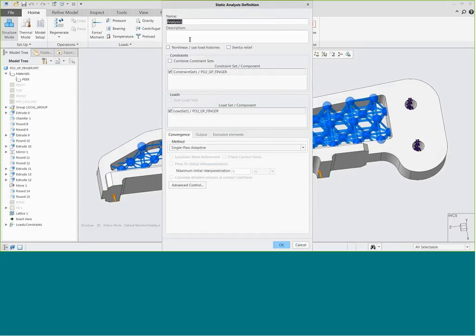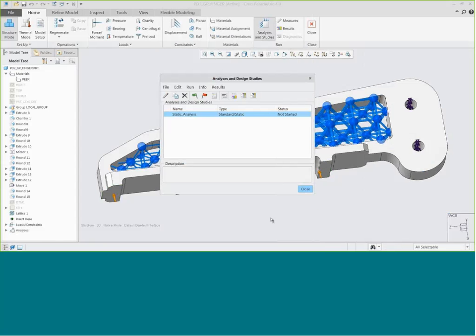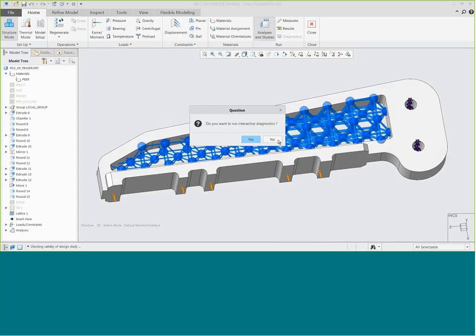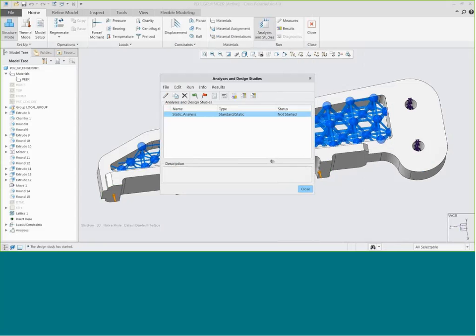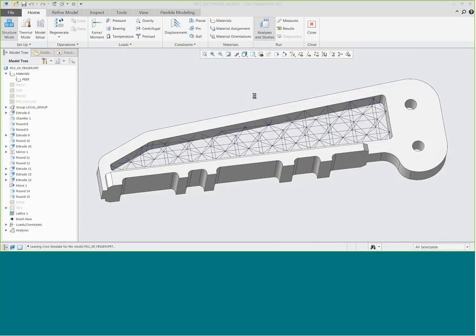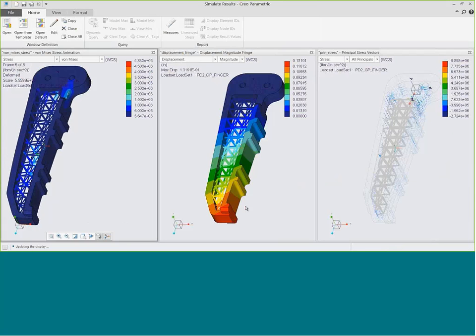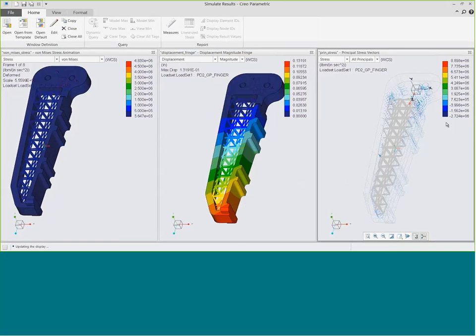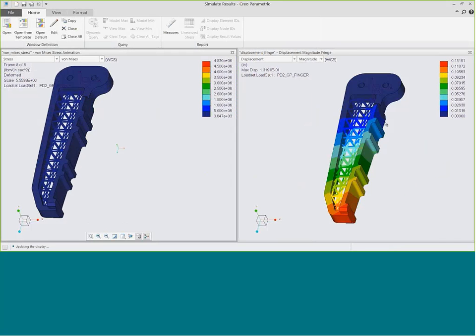Whilst the original point of having a lattice structure wasn't to use it as actual design geometry, it was there to be support geometry inside a 3D printed component, we found there's so much more that we can do with it, and being able to analyze it and manufacture it is really quite impressive. So we can see here now the deflection that we've got with that loading and a standard lattice that we've implemented here.